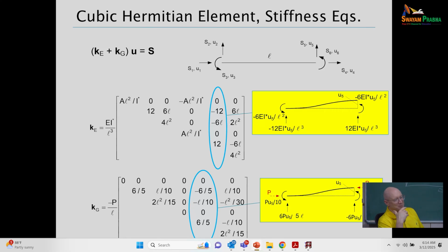From what I've seen out there, at least when I look at what is displayed graphically, I don't see software providers doing anything other than a first order analysis approximation between the nodes. They give second order forces from the second order analysis at the nodes, but between the nodes they don't consider any P small delta term. They simply interpolate with the functions. Yep.